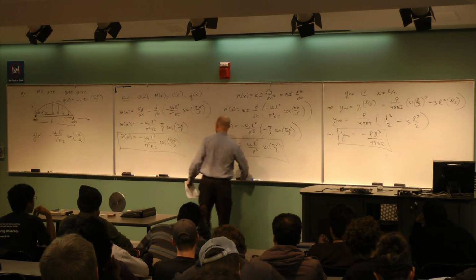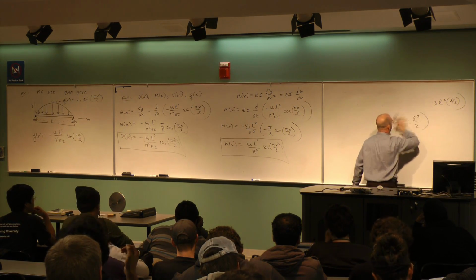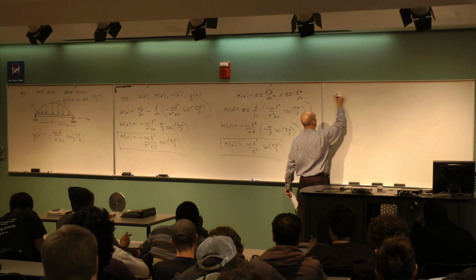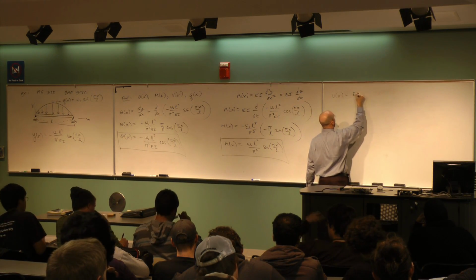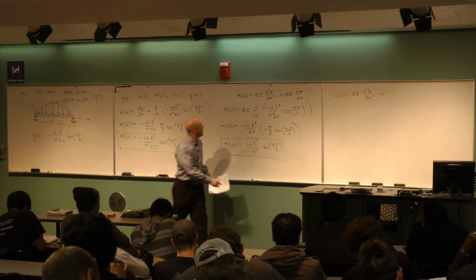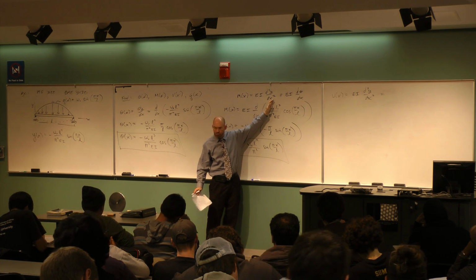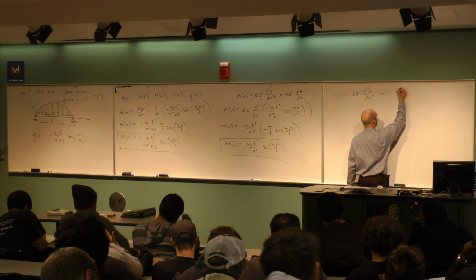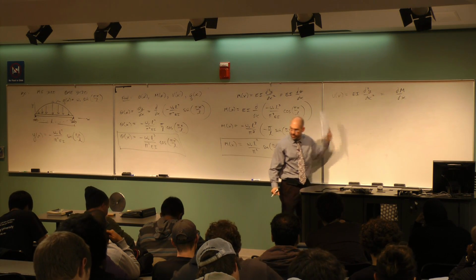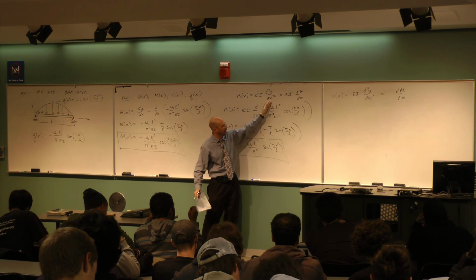All right, great. So we got theta, we got M. How do I get the next one? Shear, V of x. Well, it turns out the V is just, by definition, V of x is EI times the third derivative of y with respect to x. Now you've got to be careful when you look at this. M was already EI times the second derivative. So EI times the third derivative is just the derivative of M. Right? It's not EI times the derivative of M. The M already has the EI in it. This is M right here. So one more derivative of this, the EI stays, I get the third derivative.